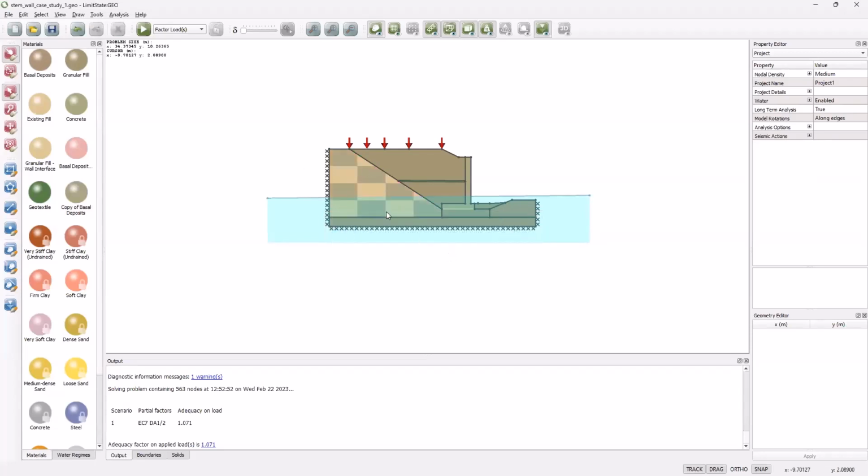add that. So what we get is a combined material with effectively two yield surfaces, and the software will always take the lowest part of the yield surface. So you can basically bracket a curved surface with a set of tangent lines, and that's how one can model a non-linear model, and that will work perfectly well with the optimization within the software.